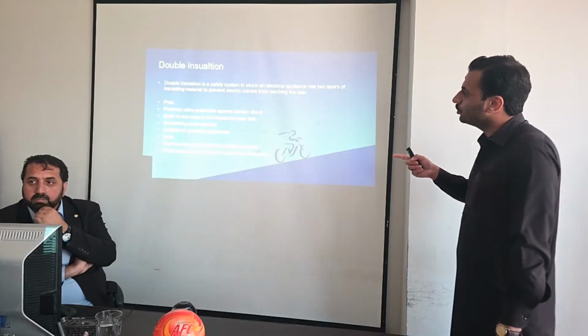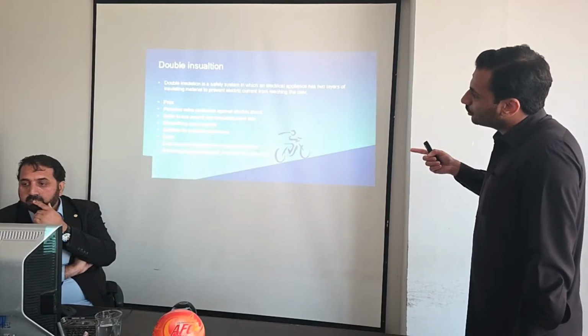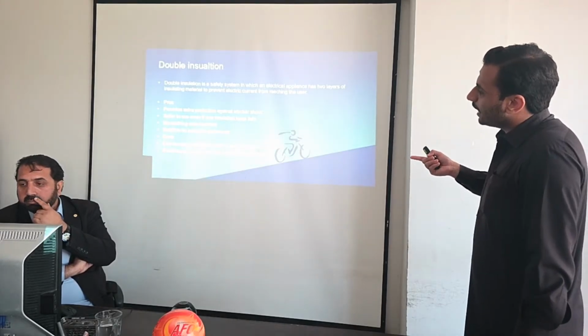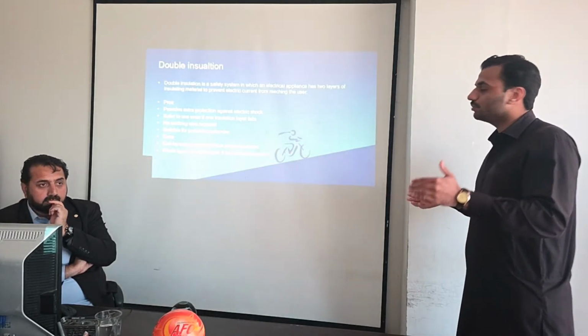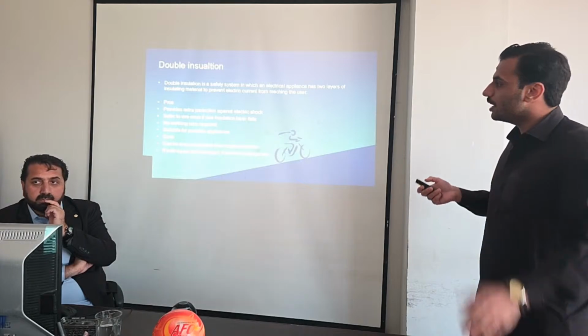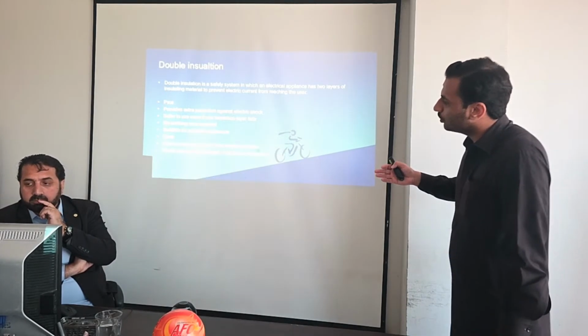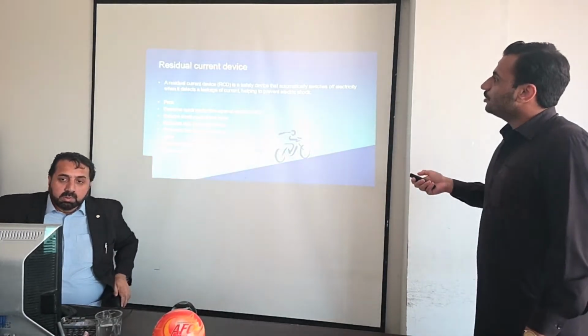So what are the pros? Provides extra protection against electric shock. It is safer to use. No earthing wire required, suitable for portable appliances. Portable means mobile appliances which you can take from one place to another. What are the cons? It can be more expensive than single insulation. If both layers are damaged, it becomes dangerous, obviously. Very good.